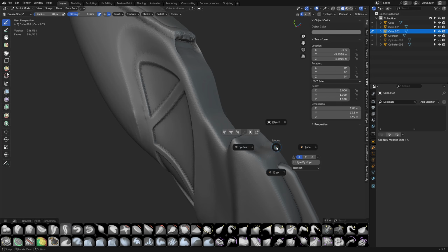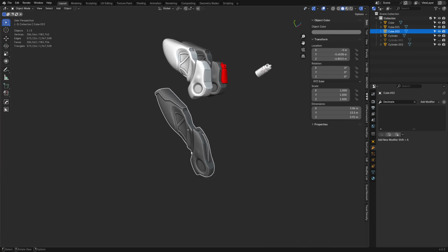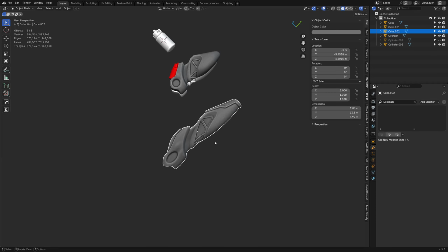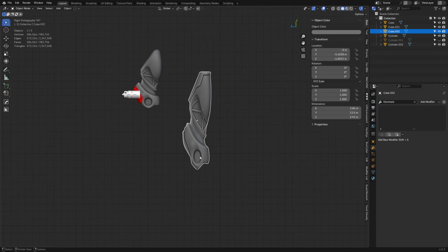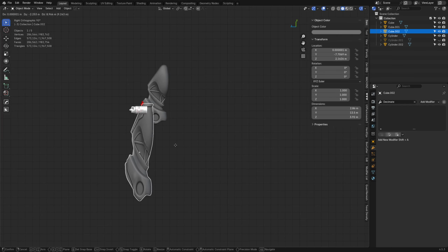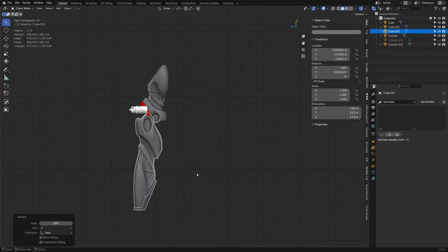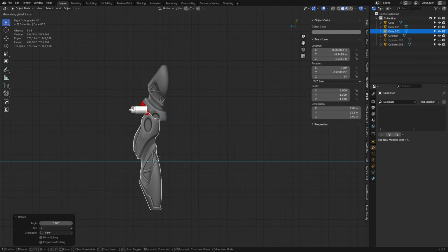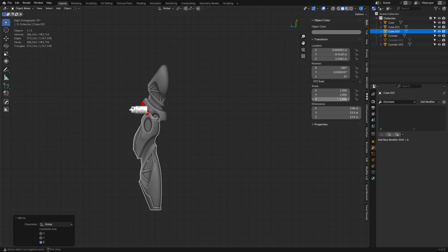The whole point of this piece, anyways, we got sidetracked by sculpting on it, was just to prove, like you can see our circular shapes have now become oval shapes, that you can use these in combination with each other. You can still mirror these, hitting Control M, X, Y, Z, or middle mouse clicking is a fast way to do that as well. It's going to invert your scale, so Control A, apply scale.